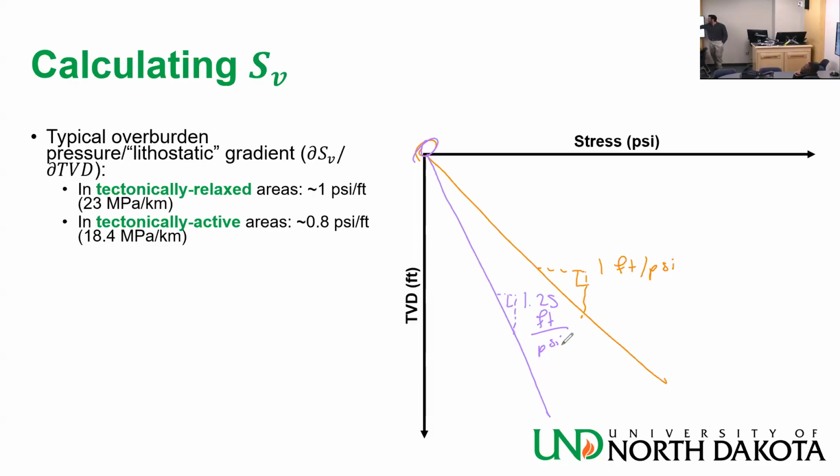this represents a smaller gradient, right? A smaller lithostatic gradient. Remember, there was a little bit of confusion when we were doing the hydraulic loop. After you go into the drill collars, the pipe becomes smaller, there is bigger friction, and the line becomes steeper because you lose more to friction. You have a smaller overall gradient, so it should appear steeper because this is feet over PSI, right? That's why. So if your PSI over foot becomes smaller, the line should become steeper.